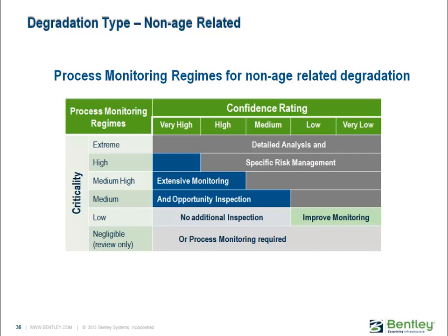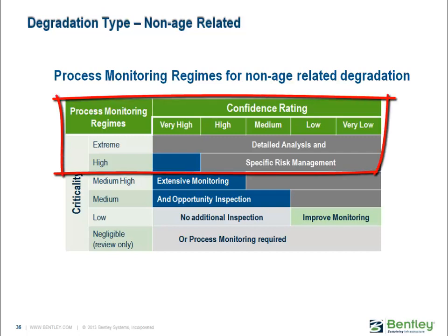As you can see in this table, if the asset has a high or extreme criticality, regardless of any kind of confidence rating, a detailed analysis is required to specify what process monitoring regimes should be applied to those assets.